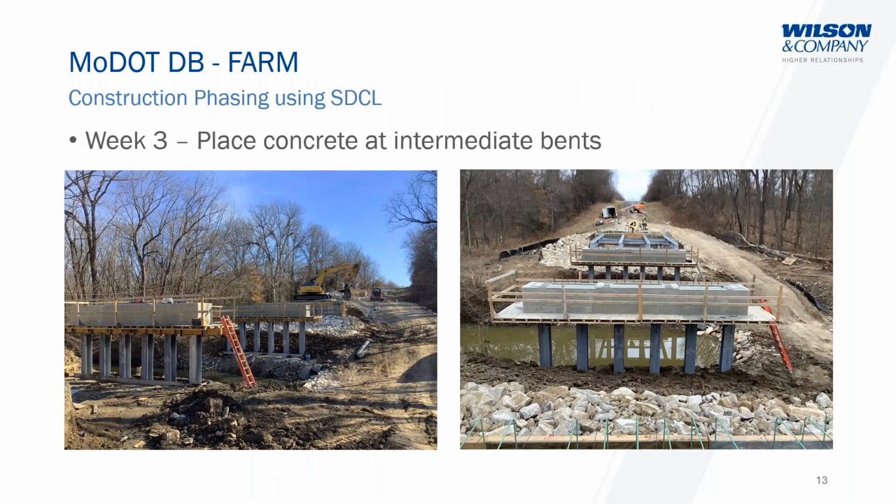Pretty solid example. One of the advantages that we did use pile vents up here in the northeast and northwest part of Missouri. They have some soils that were pretty scour unfriendly, if you will. So the unsupported lengths on those piles were pretty large. We had a number of piles on this, but having a superstructure weight that was minimized by the use of steel as opposed to concrete helped with this.